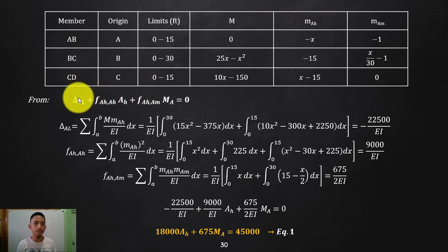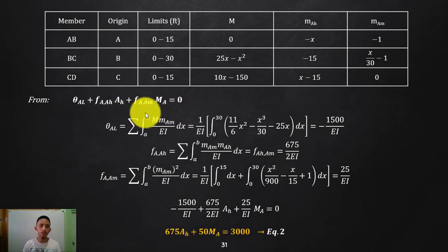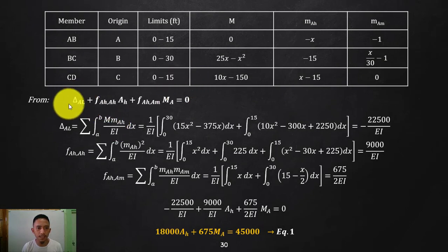And we are talking here of the horizontal deflection. But later on, when completing the equation of rotation, we will be using the virtual loading of your couple. Since again, if you're after a rotation, apply a virtual load which is a couple. So that will be your small m later on. So now this is big M and then small m AH, since we are talking about horizontal displacement here.